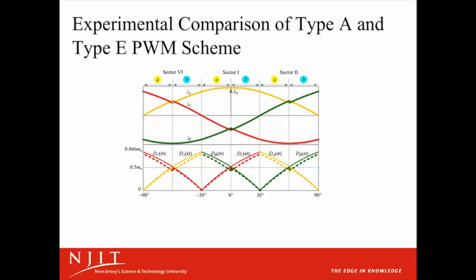In order to produce the phase current with the shape of a sinusoidal waveform, the duty cycle on each phase should also have a sinusoidal shape that is proportional to the phase current. So the input current duty cycle must be a sinusoidal waveform in order for the output to have one too. However, as represented in the figure right here, the effective duty cycle, the shaded area, is lower than the applied duty cycle in the sinusoidal shape.